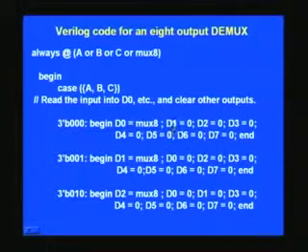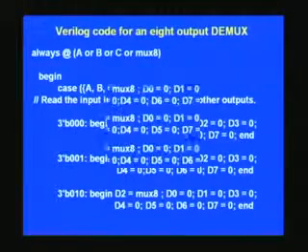And you may notice that this is done deliberately for every value here, but this need not be done. You can even put all of this from D0 through D7 right before this case, just after the begin, put that as a single statement and dispense with the use here. And you can just stick to whatever output that you want, only that needs to be listed. I have made it deliberate in order to drive home the point that we should not forget this. Whatever is to be forced to 0 will have to be deliberately forced to 0. Otherwise, the tool will not do that on its own accord.